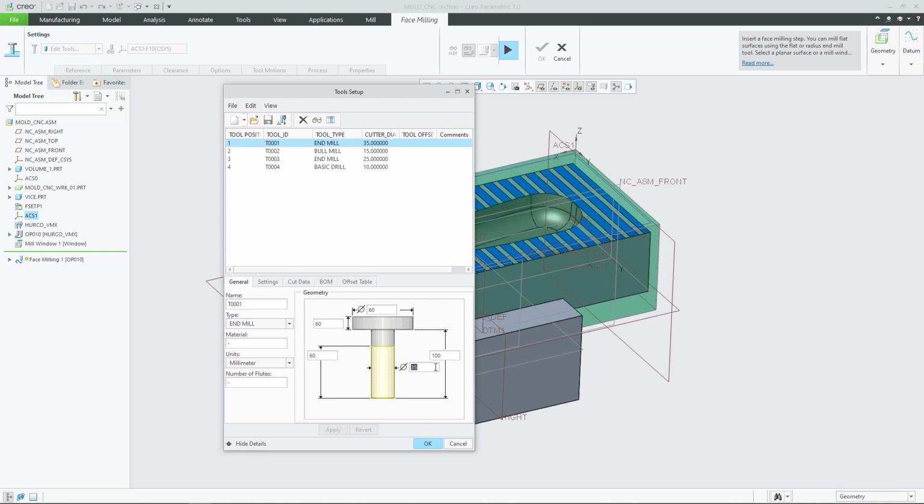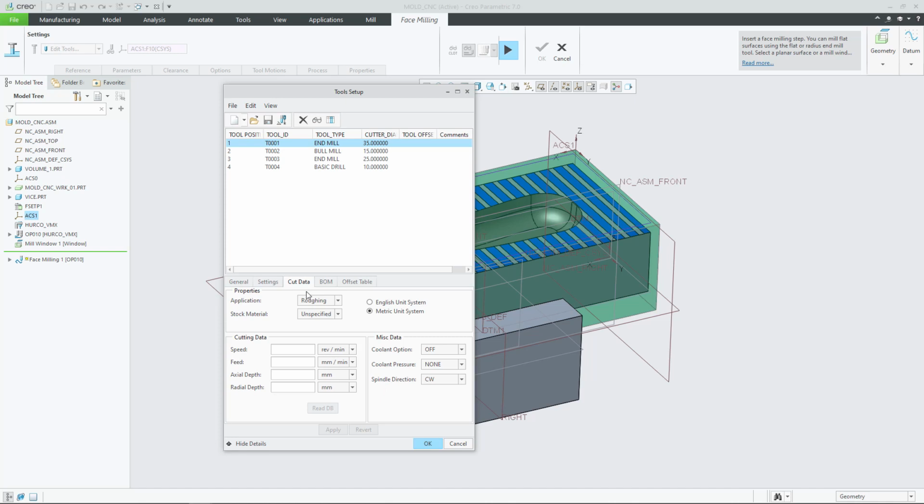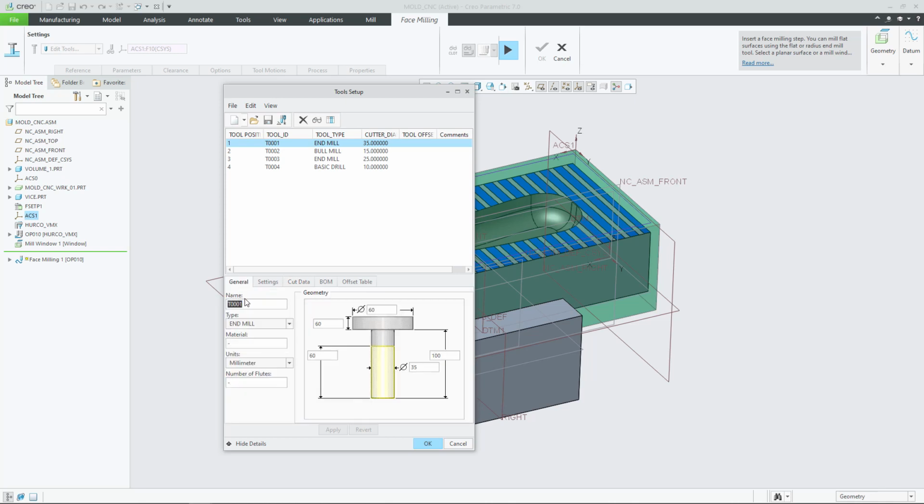We then created a common diameter of face mill that is freely available. And what we're going to start to do now is to research whether this tool geometry that we've entered here and the cutting data that we haven't yet entered, we just accepted the default that the system decided for us. So whether all of this data, the geometry and the speeds and feeds and the depths of cut and the step over distances, are reasonable values.